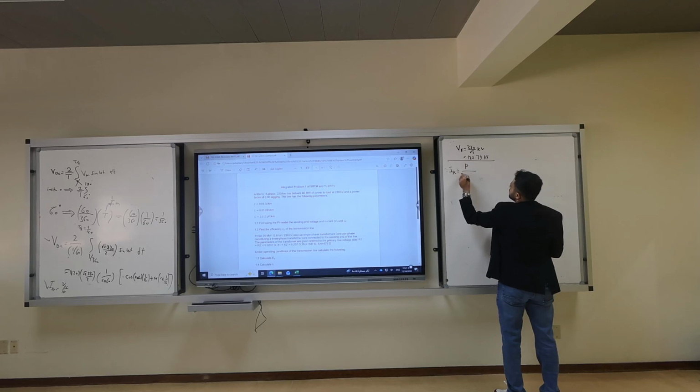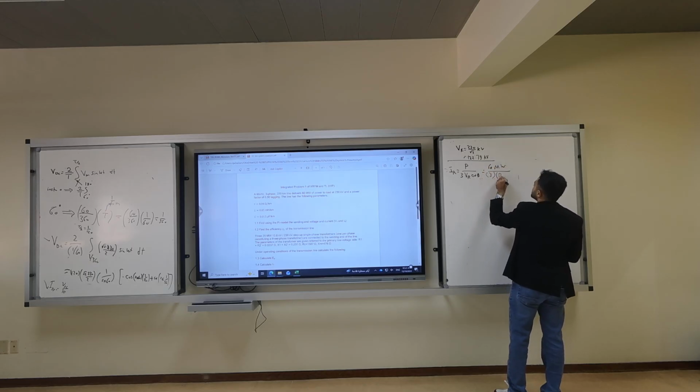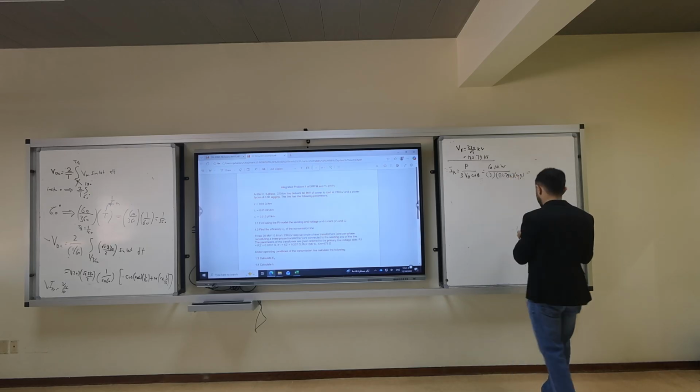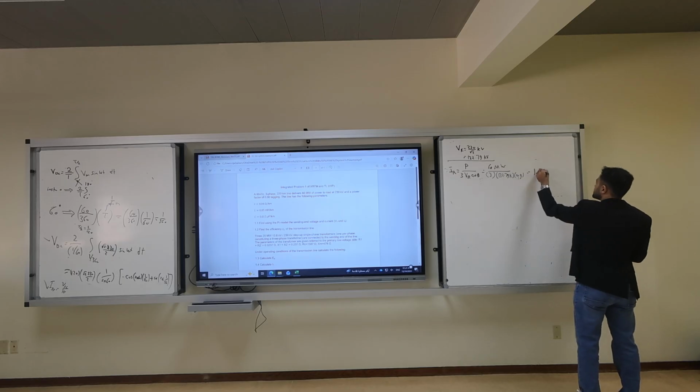Is P over 3 VR cosine of theta, which is 60 megawatt over 3 times 132.79 kilo times 0.9. You should get 167.34.